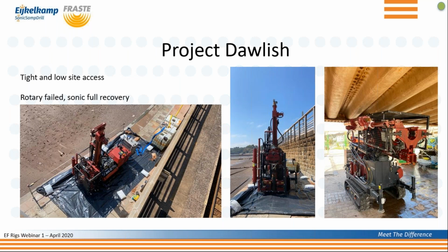And once it was in, basically they had the rotary rig on there, drilling down to anywhere between 15 to 18 meters. But throughout the whole hole, there was no recovery. All they were doing is just washing everything away. And with a 1.5 meter run, that would probably achieve 0.3 of a sample.